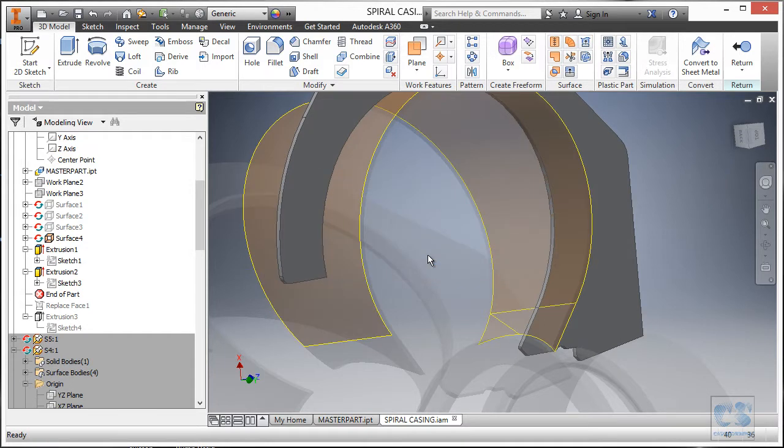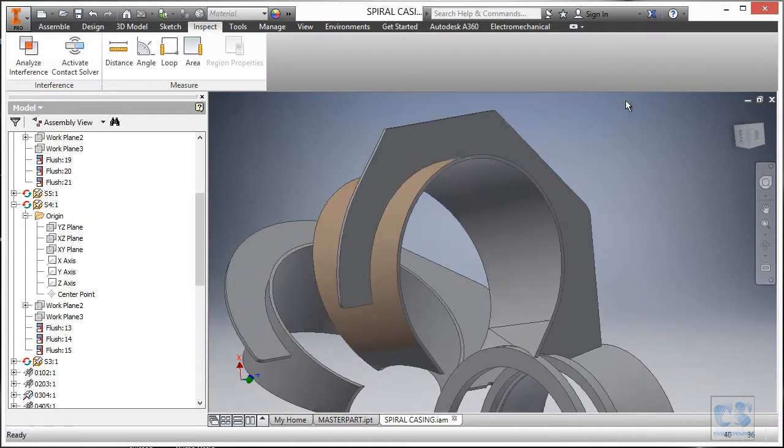And this happens because somehow you cannot extend a surface when working in the context of an assembly. I cannot say if it is just a bug or if it is like this by design. So we are going to have to return to the assembly and open the component in a separate window. And maybe we should save the part first. So let's try this and return and open the part